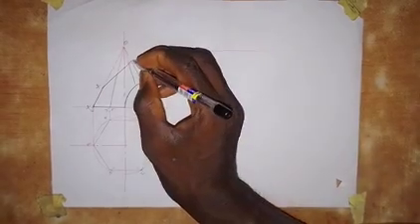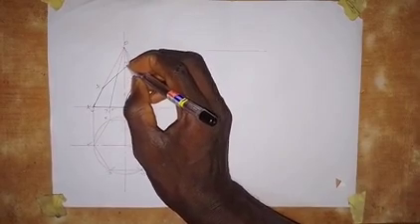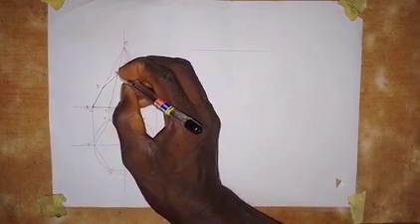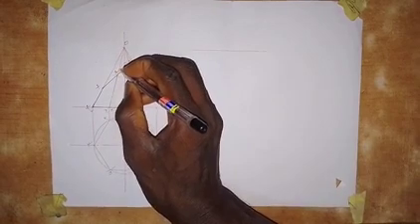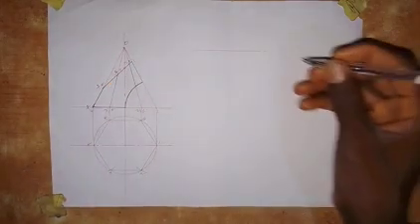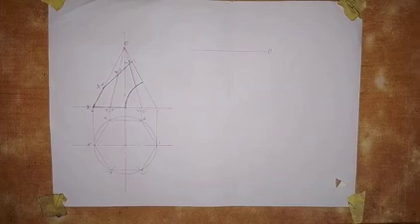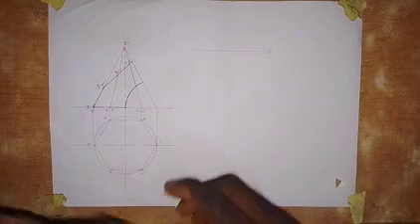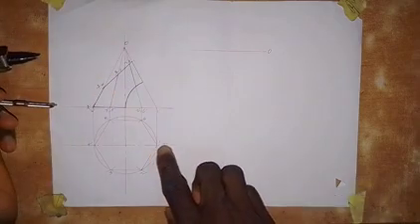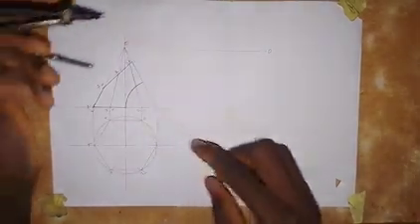Alright, so let's take note of the numbering that we have done. This is also point 1, this is 2 6, this point is 3 5, and then this point is 4. So let's take note of that. This point will be point O, that is the apex of the pyramid. All we have to do now is to take the true length. This is the true length since the corner is on this horizontal. So this line O1 prime is the true length.